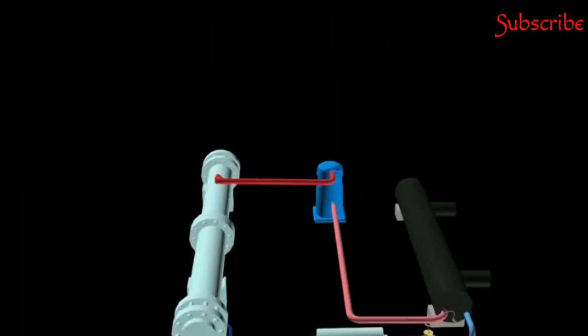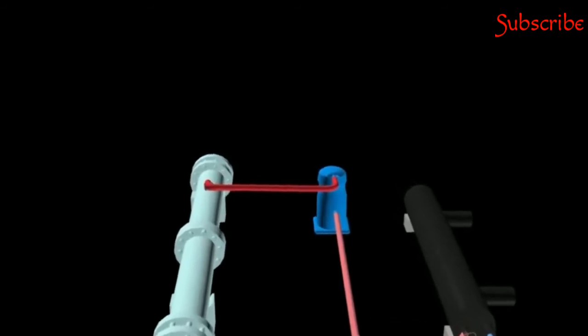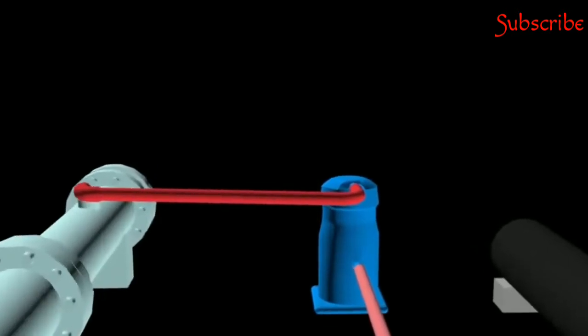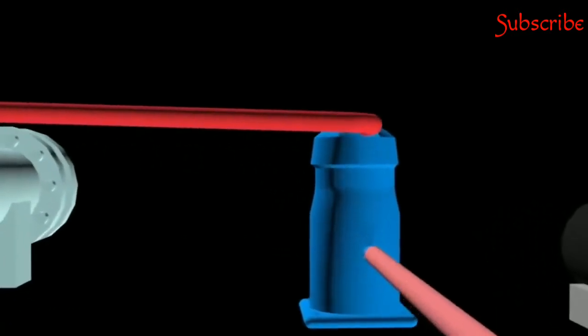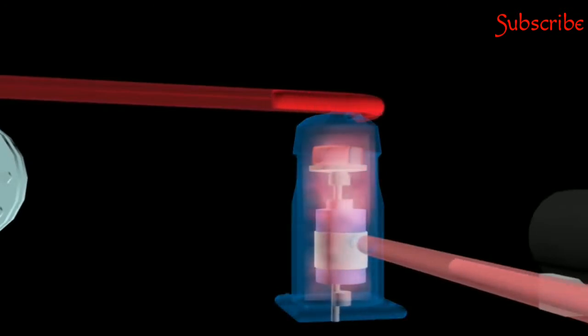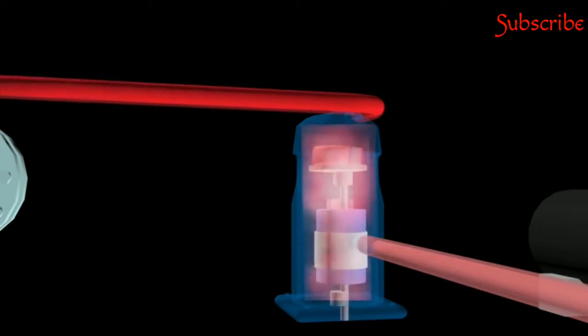Compressor. Compressor works to increase the pressure of the refrigerant. In addition, it also serves to increase the temperature of the refrigerant higher than the temperature of condenser water so that the heat transfer can occur in the condenser. The refrigerant enters the compressor as low pressure gas and goes out as high pressure gas.